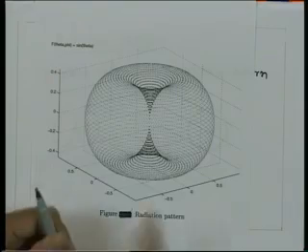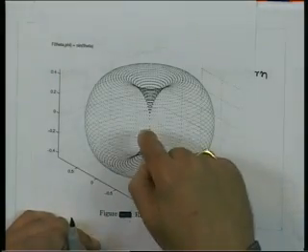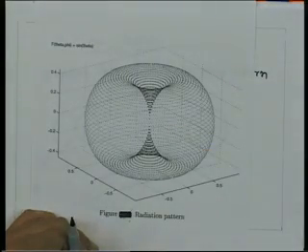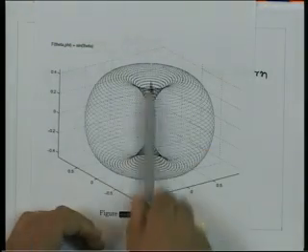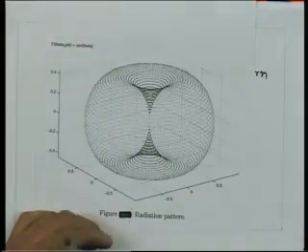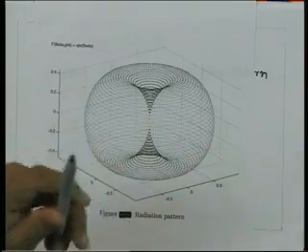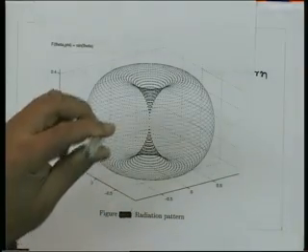The maximum power goes in the plane which is perpendicular to the Hertz dipole. The Hertz dipole is oriented this way, that is where the dipole was oriented. Along the dipole there is no power flow, and that is a very important thing: if I consider an antenna like a Hertz dipole, there will not be any power radiated along its axis. The whole power will be radiated perpendicular to that, and in this case the power will be radiated symmetrically in all directions.